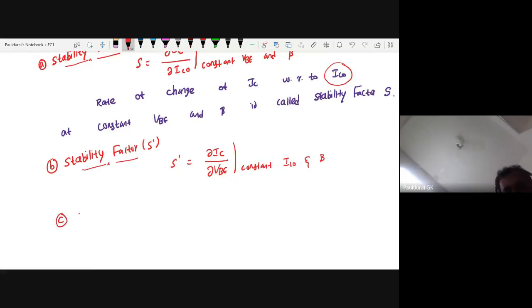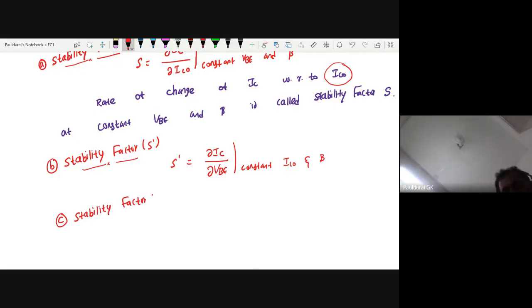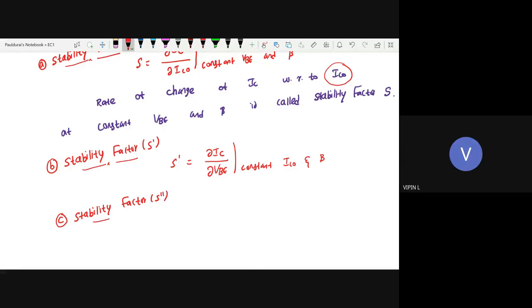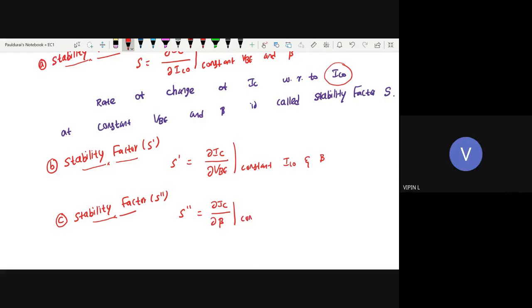Vipin, are you there? Yes, sir. What is stability factor S double dash? Sir, rate of change of IC with respect to beta, at constant VBE and ICO. Thank you.